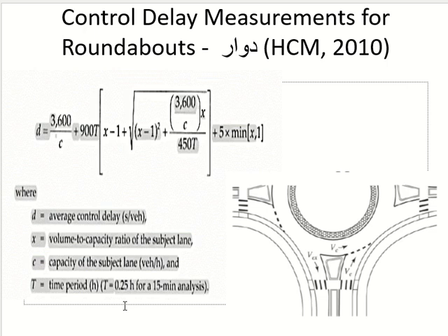Then the next parameter is T. T refers to the time which is taken for flow observation. So normally we take the flow for how many minutes? 15 minutes, right? And we want everything in hours here. So 15 minutes means 0.25 of an hour. And this is the case most of the time. So T in most of the cases will be 0.25. Clear?